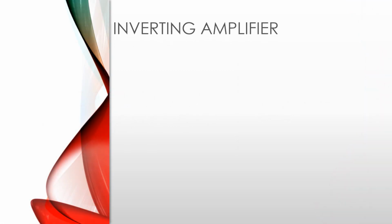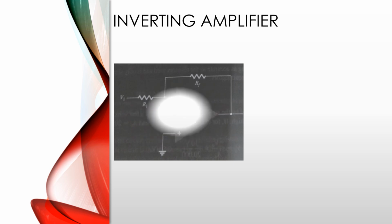So what is the inverting amplifier circuit? This is the inverting amplifier circuit by using op-amp. Here one input resistor is connected at the inverting terminal and one input voltage is connected at the inverting terminal. The non-inverting terminal is connected with the ground connection, and this is the inverting input terminal and this is the output terminal.